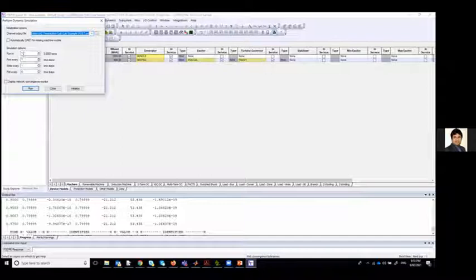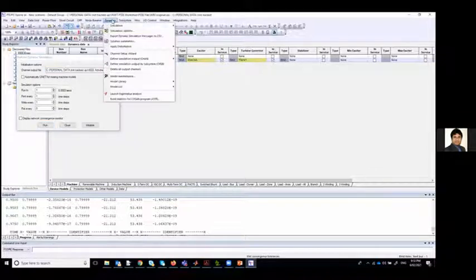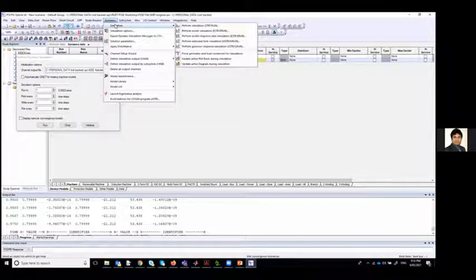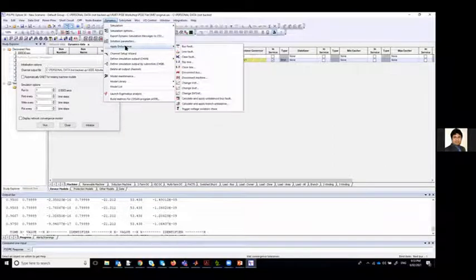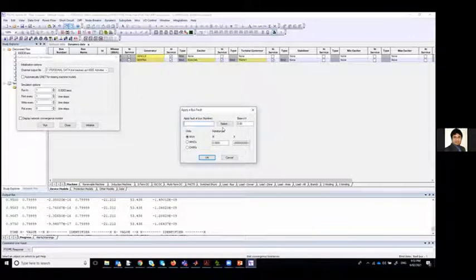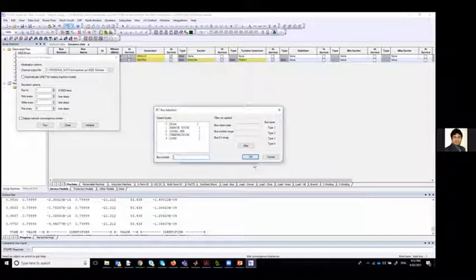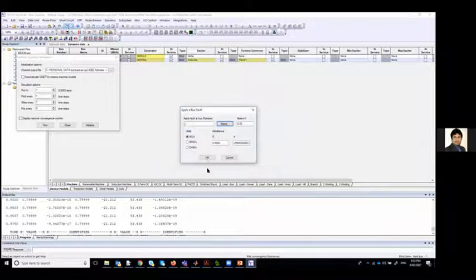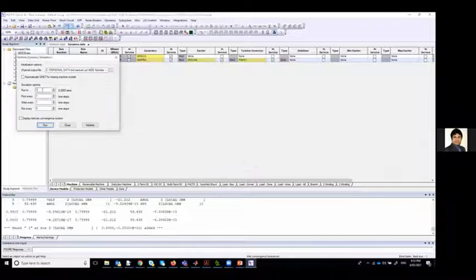Now I've run the system up to 1 second, then I want to apply a fault. Let's say I want to apply the fault at 1 second. Apply disturbance, click on apply disturbance. I want to apply the fault at 1 second at the generator bus, let's say. I want to keep that fault for 3 cycles. That means, let's say 0.06 seconds. It's up to you actually.